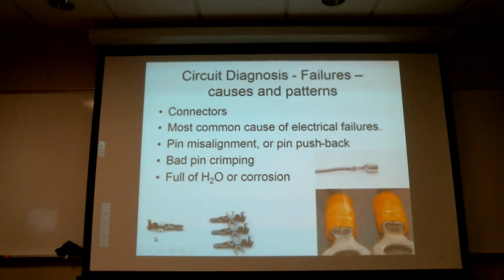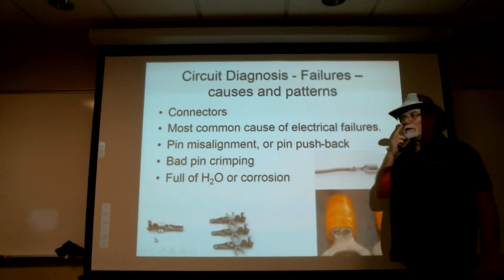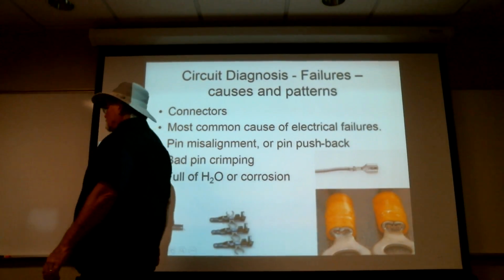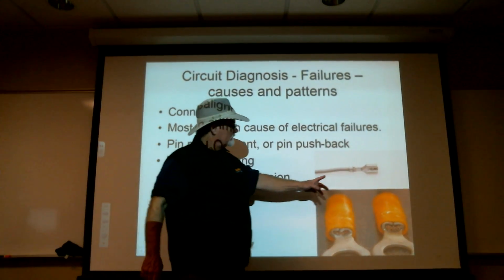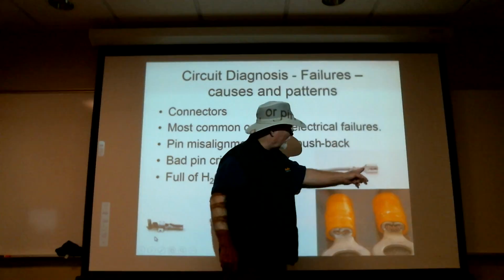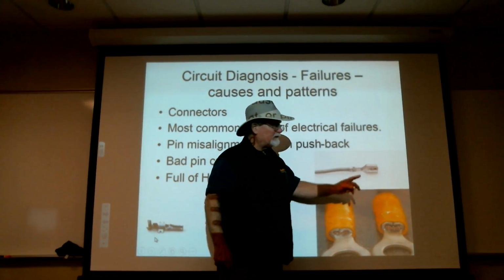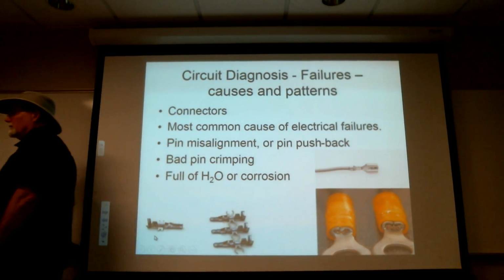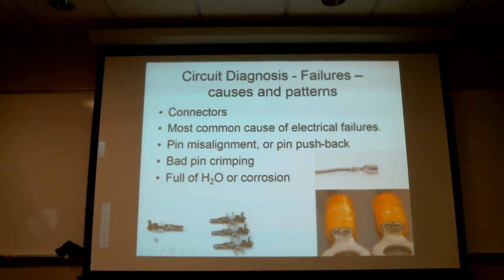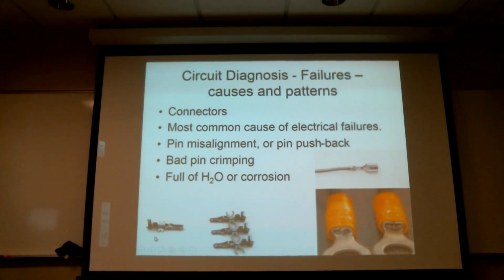But the only way to make that just a little bit better is put a little strain relief on it, or put it in a housing that then provides a strain relief. That's a connection that, as long as you don't submerge it, will last forever. And it's because it's crimped really well here, all of this is nicely sealed. So even if it did get a little bit moisture in there, it wouldn't work its way in and start corroding.